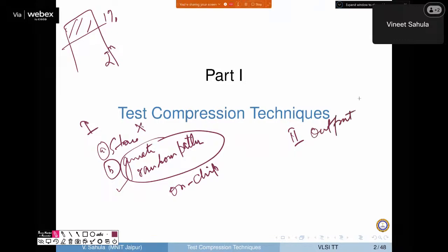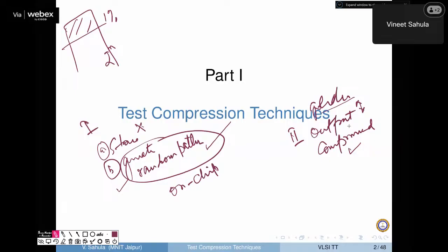Output pattern or golden output in compressed form. I'm storing golden output in compressed form. Surprisingly, the solution to generate random patterns and the solution to generate compressed output, and the storing of golden pattern and matching it with the current output, the circuit required is the same.